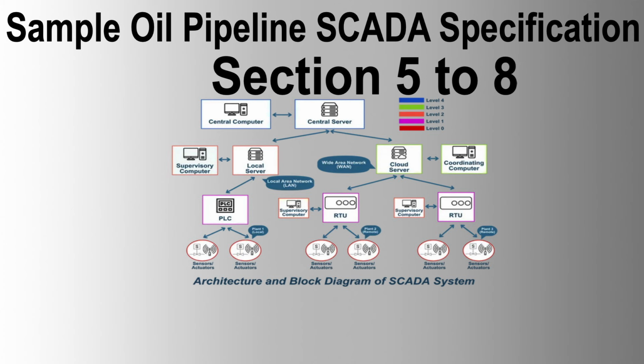5.7.1 Construction of enclosures. Enclosures for remote sites shall be constructed to withstand environmental conditions, including high temperatures and dust. Features include insect, weather, and vermin-proof construction. Lockable with cam locks and fitted with sunshades. Internal temperature sensing device and loss of cooling airflow detector. Rounded edges and folds to avoid stress cracks and irregularities. 3-point latching doors with a minimum access way clearance of 2,000 millimeters.